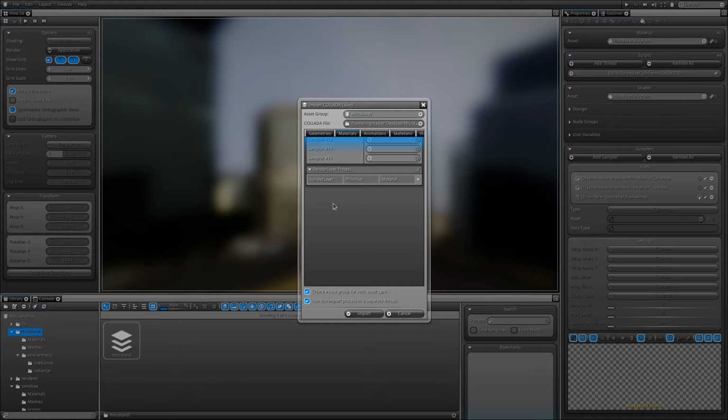We have cascaded shadow map that is implemented. So before drawing our scene, shading our scene, we need to first grab the depth to be able, later on during the shading phase, to calculate shadow. So we need to have all objects that actually cast and receive shadow placed on our right depth render layer, which is the first render layer. If you check in scene and the render layer, it's our first render layer pass. So we need to ensure that all new objects will be placed on that right depth render layer first.